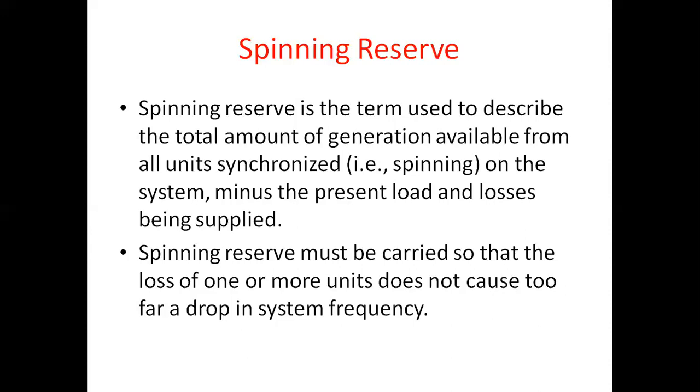So, in order to run the entire system at a constant frequency, we have to provide the conception of spinning reserve in the system. Spinning reserve must be carried so that the loss of one or more units doesn't cause a large drop in the system frequency.